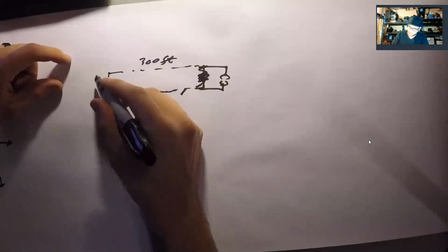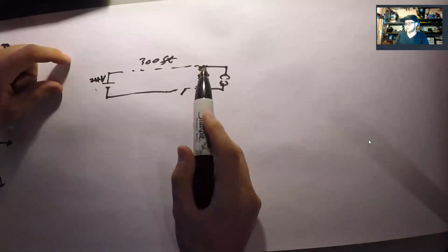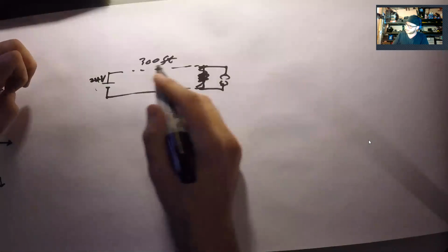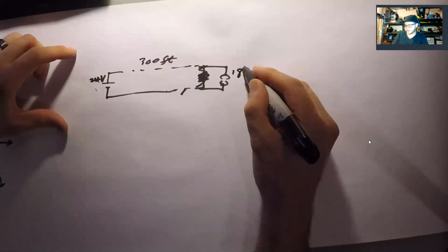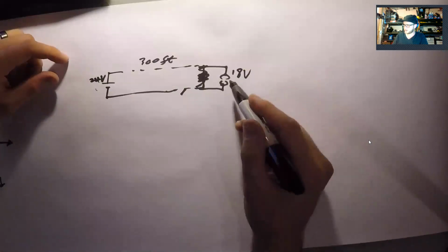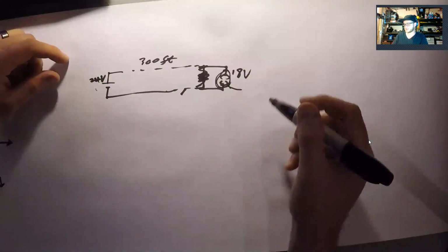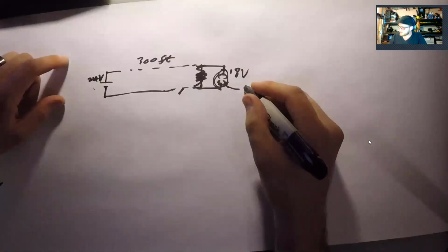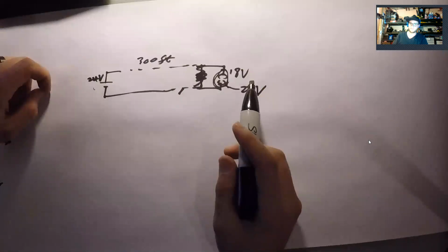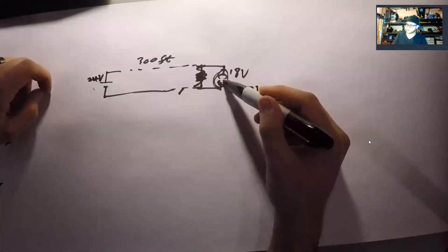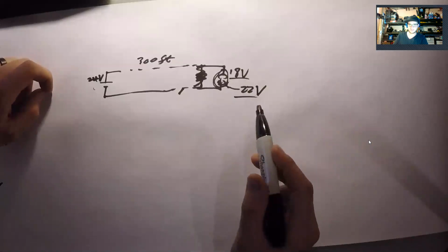So here, this voltage potential is 24 volts. But when I run through all this wire, this may have degraded to like here across this contact, 18 volts or even lower, right? And if this module here on the receiving end is sensitive, if it has a threshold voltage of like 22 volts, this signaling may not work, right? Because when I close the contact and complete the circuit, it's only seeing 18 and it needs 22.